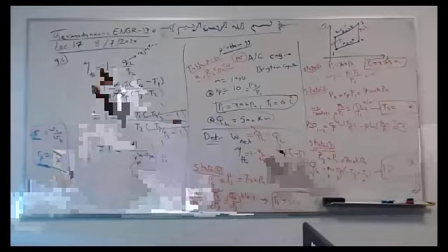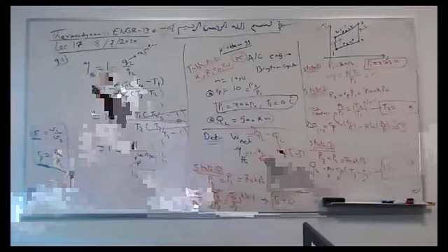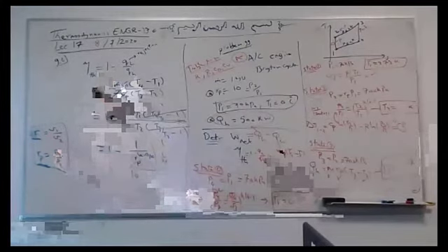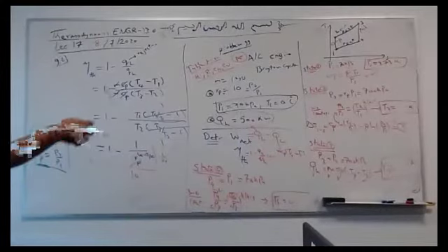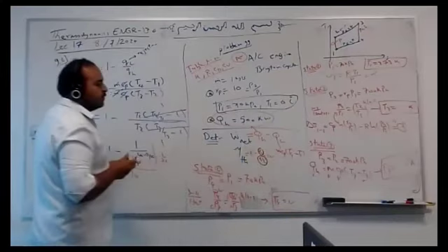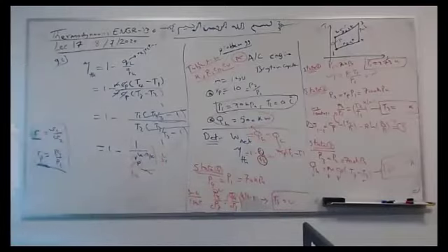So for everyone, if you have the compression ratio, the volume, the pressure, if you have all of these, you can easily get the efficiency. So this is a good check for you to make sure that all the temperatures are correct, including T1, T2, T3, and T4, all of them. So you can get a good evaluation for your calculation. And of course, use this one. So both of them together work as a good check for you.